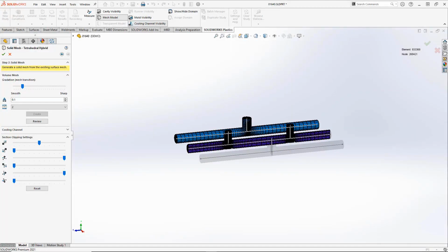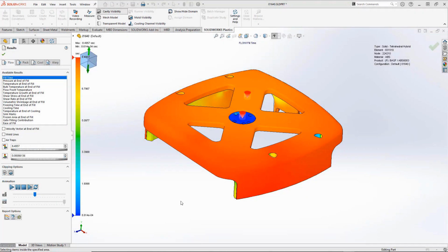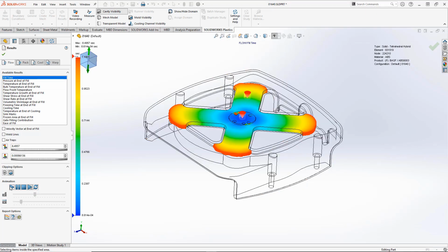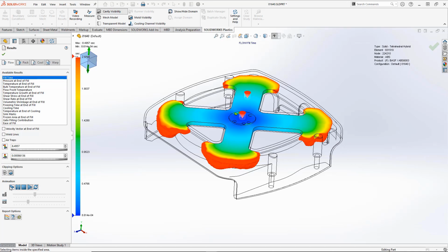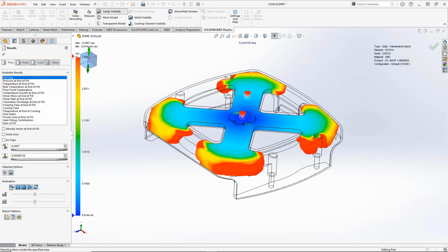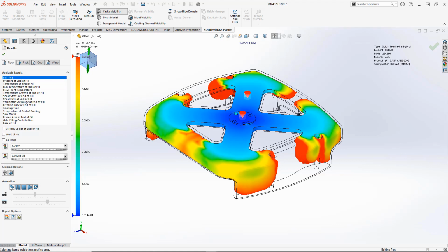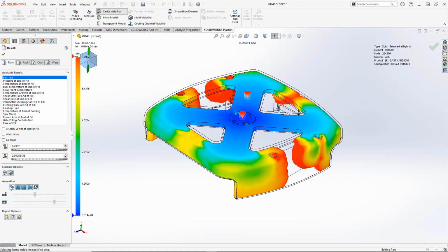By defining the entire simulation on the 3D model and the virtual domains, it has enabled a more dynamic workflow where you can look at and evaluate different scenarios in your design before any of the heavy lifting is done. The results themselves, which include the new multi-material overmold injection process, are now more accurate when considering cooling, giving you confidence in your injection molding process before you even start designing or investing time and money into the mold itself.